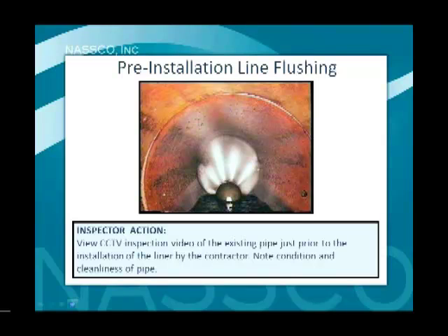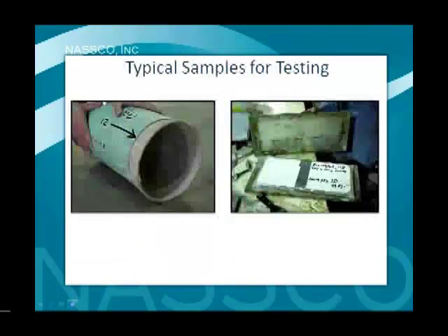One of the very primary things you need to do to get as good an open barrel pipe as you can is to have the contractor run a CCTV camera down the pipeline immediately prior to doing the liner. Things happen overnight, or a week from when the actual cleaning was done, and in brick sewers, bricks fall out of place. So it's really important that this be done, and the inspector should be present to note that.